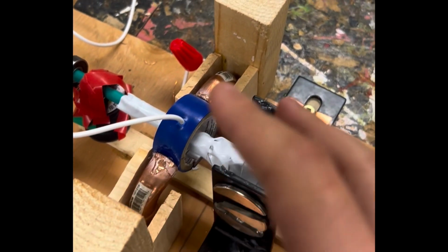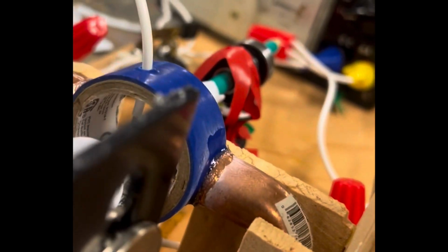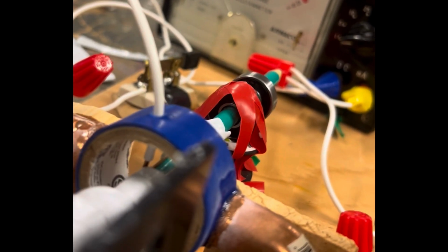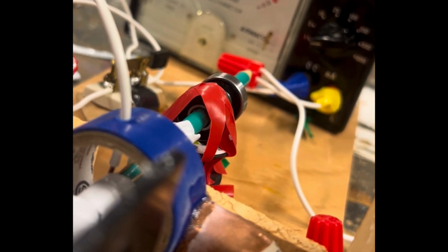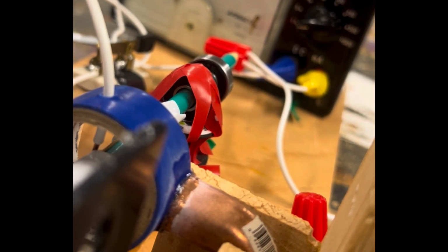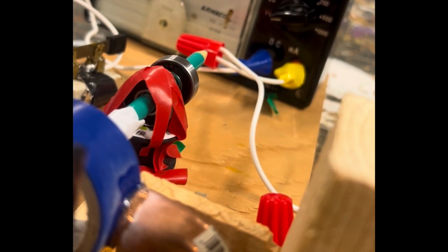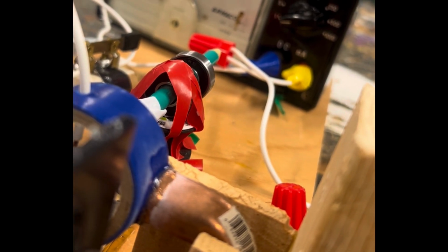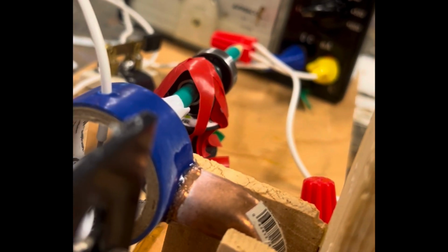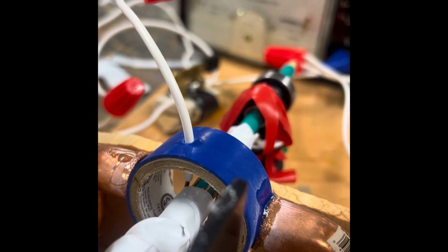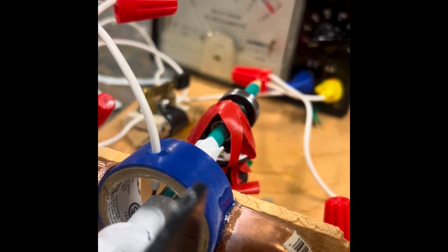It is the exact same as the motor, except here I've got this commutator set up. You probably saw that earlier in the video, unless I didn't put that in. But what that does is I've got the wire coming through the top and the bottom, just touching those. Now, the reason I couldn't get the motor spinning is this created too much friction for the motor to power. Maybe if I had added more batteries, it could have done it, but I didn't want to create a short circuit while trying to run more current through my thin enamel-coated copper wire. So I didn't put more batteries on to that.